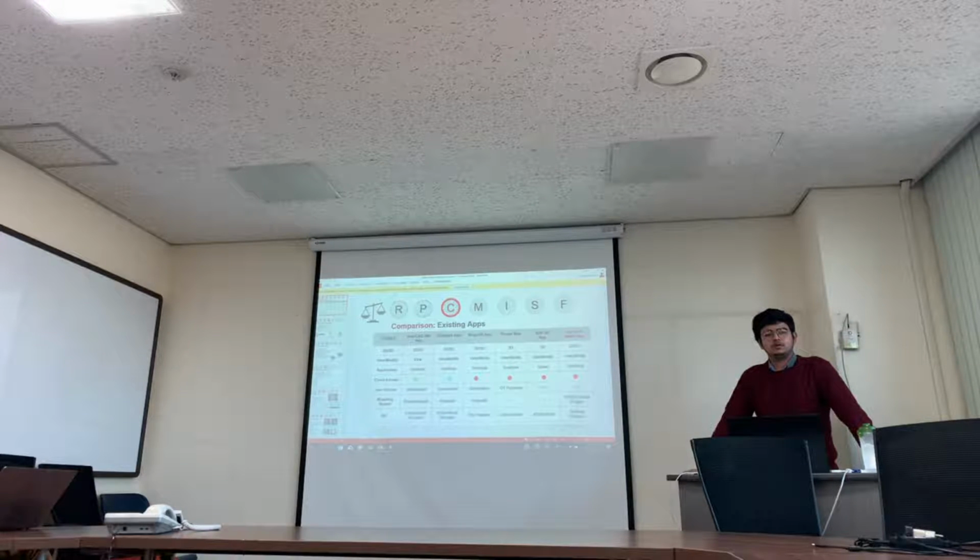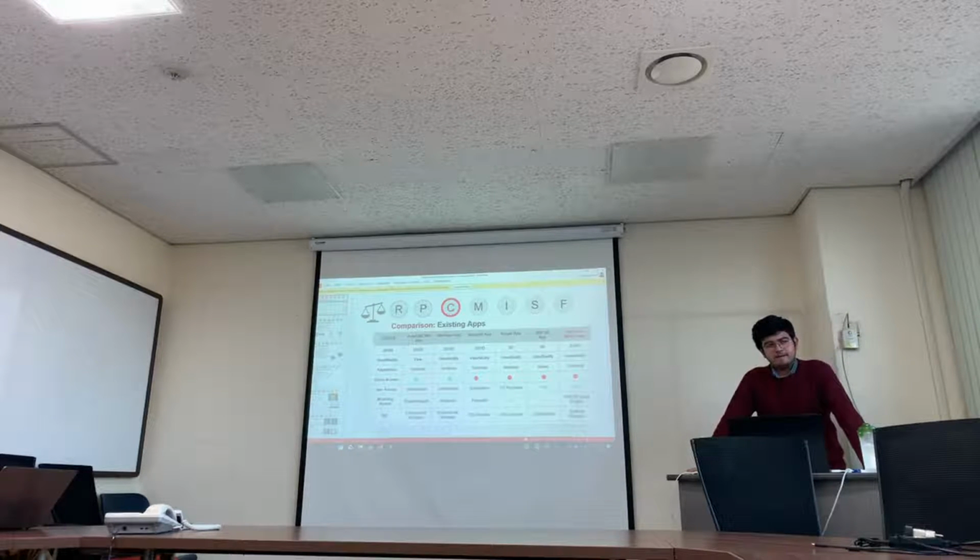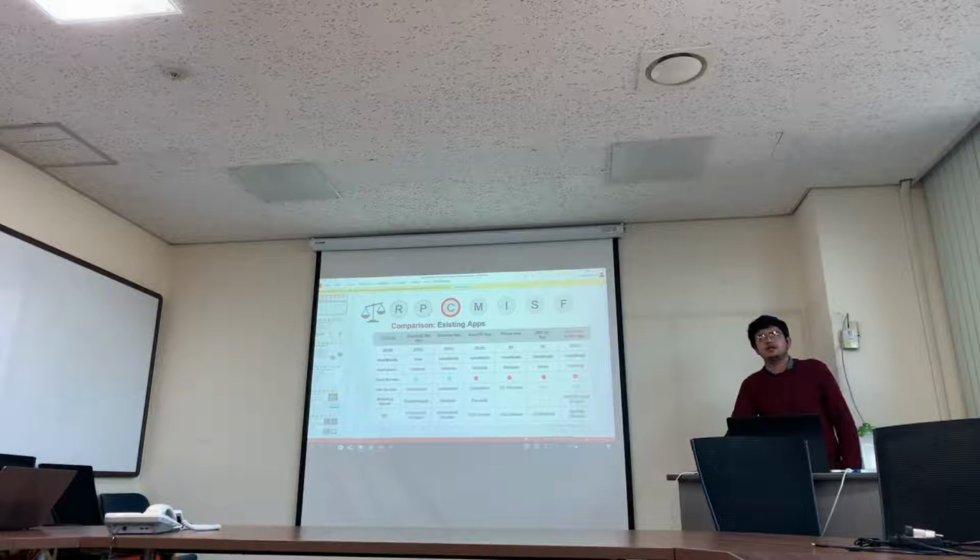I mean, you draw the sketch on the XY plane and extrude the sketch. Then the first face is on the XY plane. Then how do you determine if this is the XY plane or the face of the extrude? I couldn't understand your question. I mean, this is the XY plane. So you draw the sketch and extrude. One face of the extrude is located on the XY plane, so we don't select that face. We only select the other faces.